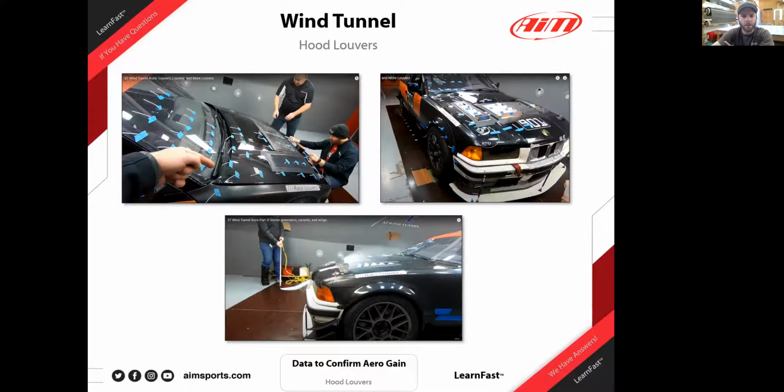Then what they're measuring is very, very good scale pads, for lack of a better word, right? For downforce. And then somehow they've got some sensors for how much the car is being forced rearward, for the drag side. So really it's 2 dimensions they're measuring. Yeah. So those scales underneath the tires measure downforce, and they measure a rearward force to measure drag.